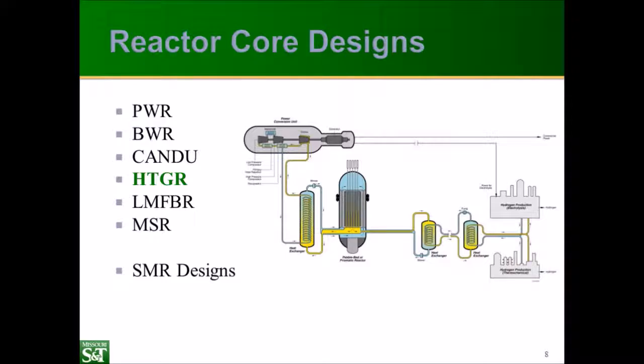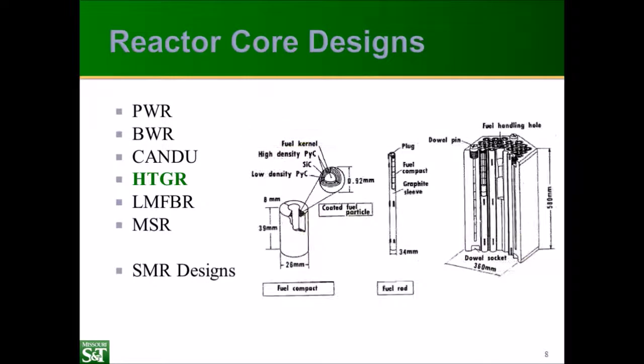Now, the moderator here has a small slowing down power, so you're going to have a large moderator to fuel ratio and a low power density. And you have to have a little bit higher enrichment for this than you do for a typical light water reactor. Well, one of the other issues here is that gas is not a very good coolant. The heat transfer coefficient is much lower for gas than it is for liquid.